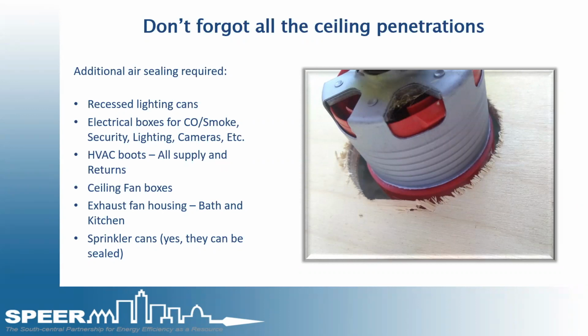If it's an escutcheon that's made of plastic and you use the wrong sealant, it can deteriorate the plastic. It can cause problems with the operation. Most of what I saw in multifamily and single family has metal escutcheon housings. Those can be sealed to the opening. Most of the time when the sheetrockers cut those openings, they're bigger than what they should be.